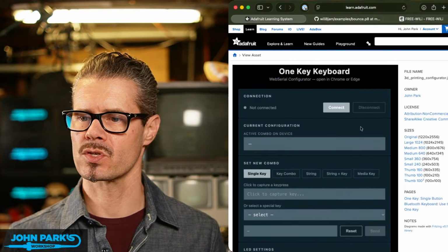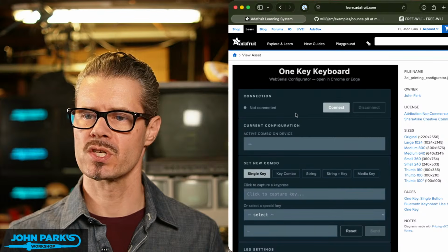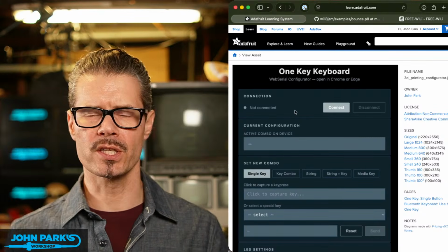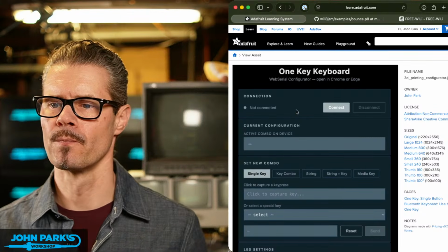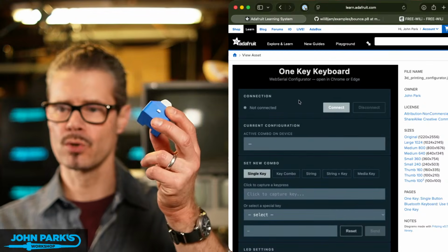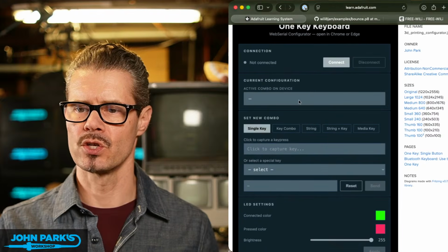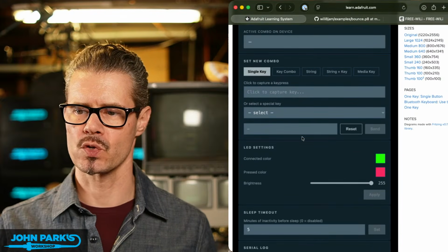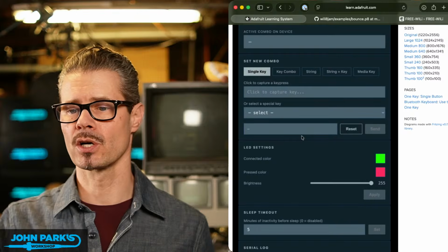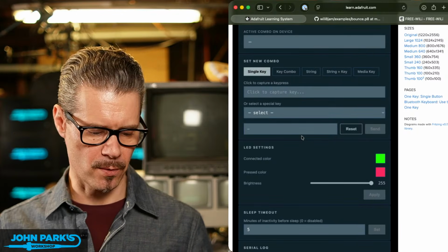web page here. So here you can see this has web serial. You'll need to use Chrome or Vivaldi or Edge or something like that that has web serial. Plug this into that computer, connect. This is not wireless. Connect over USB, and then you can do all of those serial commands with a nice GUI, including setting the color of the NeoPixels, the brightness of them.